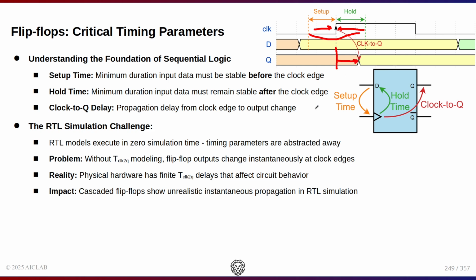In RTL simulation, we use zero simulation time. It means that we don't model timing parameters of flip-flop in RTL simulation because at this stage the functionality of design is important and we want to make sure that our design works correctly. But there is a problem here.